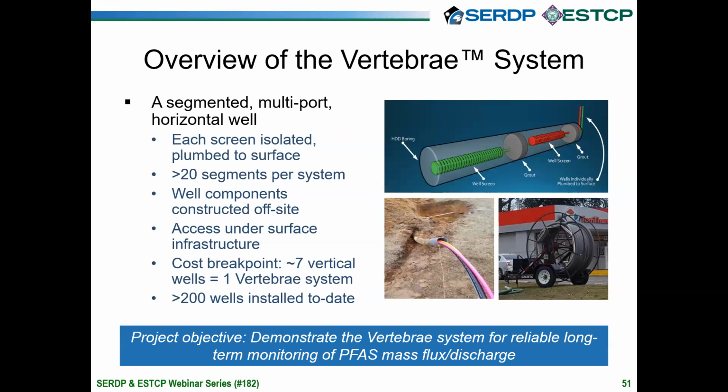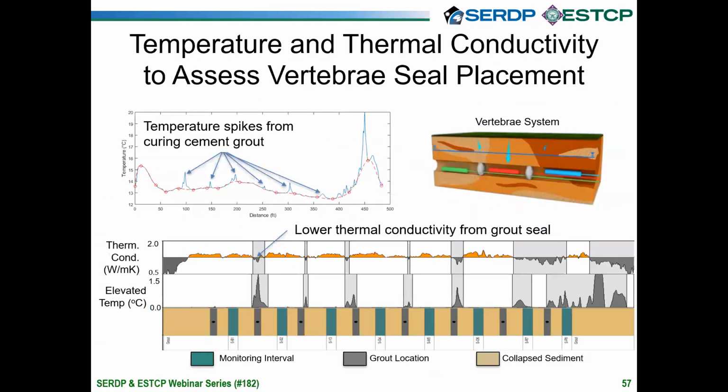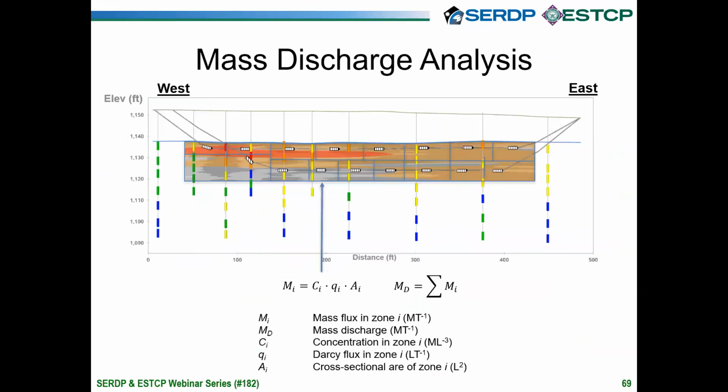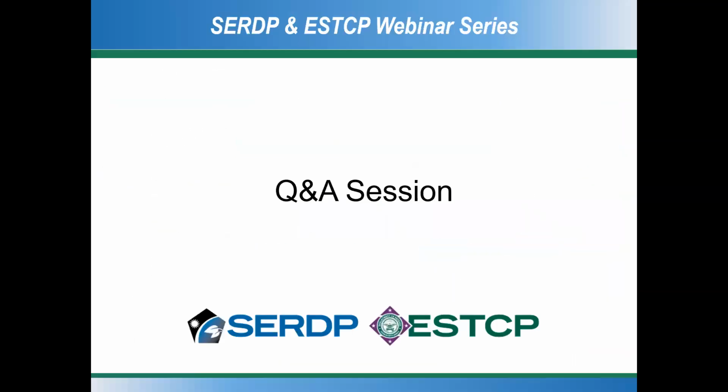Thank you. This next question is from the Colorado School of Mines. Assuming the slug test is done through the sampling pipe, do you observe any air trapping during the test? That could be an issue as well. We did 2 types of slug testing. We did this pneumatic test where we pressurized with air and then released that pressure and looked at the head rise. We also did a conventional slug test where we added water to the riser. And in both cases, I would consider the results highly suspect.